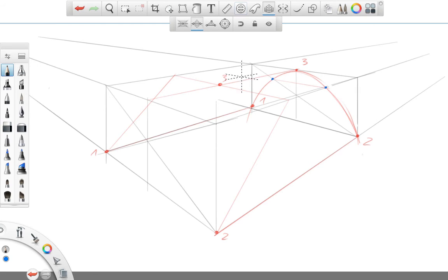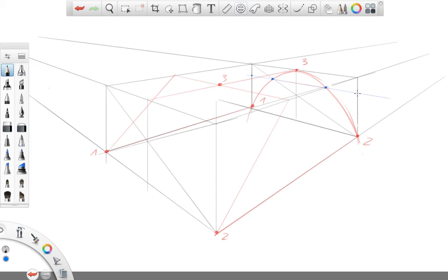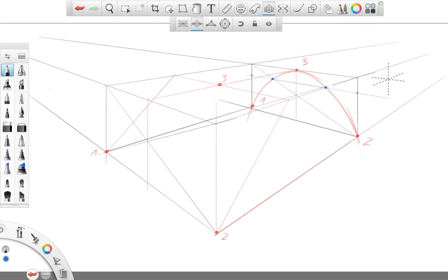From the vanishing point I will start drawing a line through there, and you see that it then touches those corner edges. And then from the other vanishing point I can draw a line through it till, as you can see, this hits the red angled line. Do the same here. And if these two blue lines are good, if I now simply draw a connection line, they nearly should intersect at the same point at the red line. And they nearly do. Perfect.